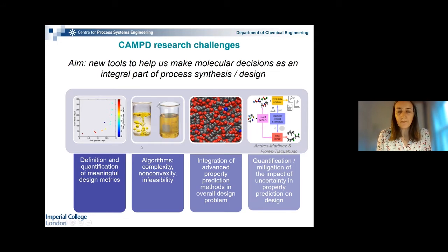We face some rather complex solution strategies because as we're changing, for example, in an absorption column or in a crystallizer, we're changing the solvent and we're letting the algorithm change the temperatures and the solvents. We have no guarantee that the solvent will be liquid as we'd expect in the process unit at that point. And so that may lead to failure of solving the problem. And so we need to control that somehow.